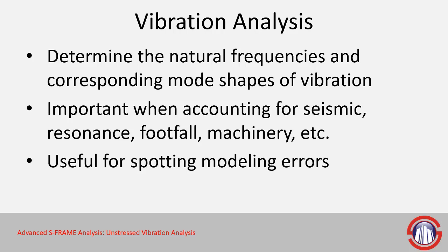Another useful reason for vibration analysis is that it's useful for spotting modeling errors early in your modeling process. Before you've even applied your loads, you can run a vibration analysis, and you'll be able to determine whether certain elements might not be connected as you intended, or perhaps the model is more or less stiff, or the mass is modeled incorrectly. Those sorts of things can be spotted with a vibration analysis.